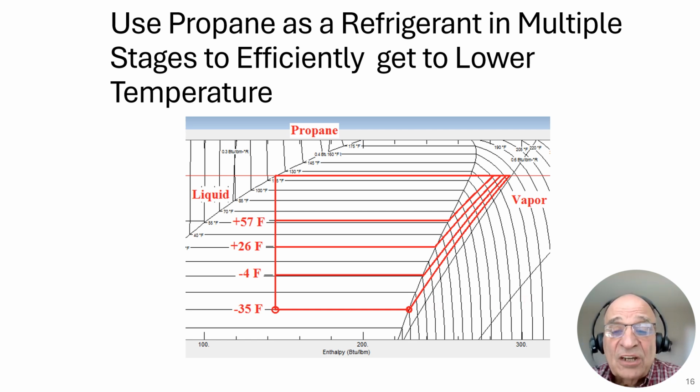What's happening in this chilling side of the refrigeration process? You have a four-stage compressor up here that is taking refrigerant from this stage at its associated pressure, this stage with its lower associated pressure, this stage with its lower pressure, and finally the very bottom stage, which I said was approximately 18 psi absolute.